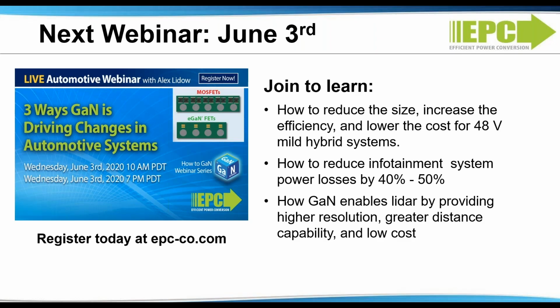Okay, wouldn't using a 100 volt device for a 48 volt input be a little bit oversized? Yeah, it's a little bit oversized. 80 volts is probably the minimum that you want to use because of overshoots and transients and things like that. If we made 80 volt FETs, they would be a little bit better, and they would be perfectly suitable for 48 volt inputs. Not so for 60 volt inputs. For 60 volt inputs, you really need 100 volt devices.